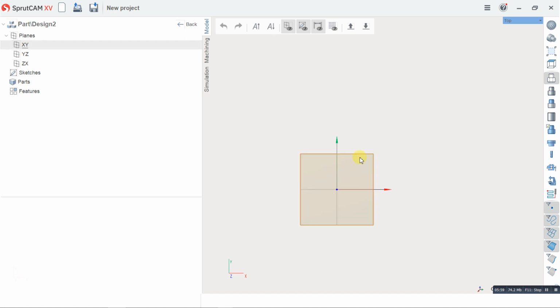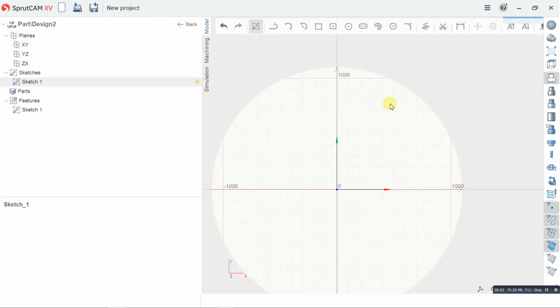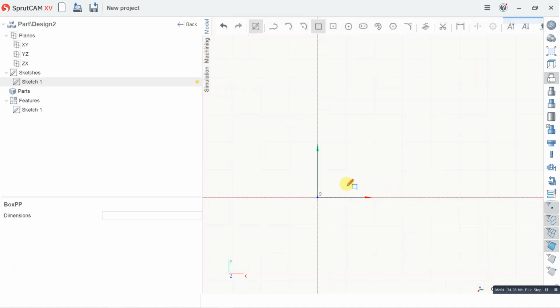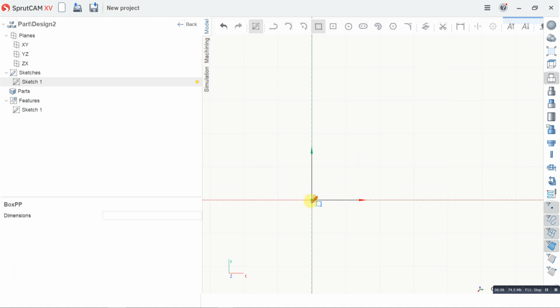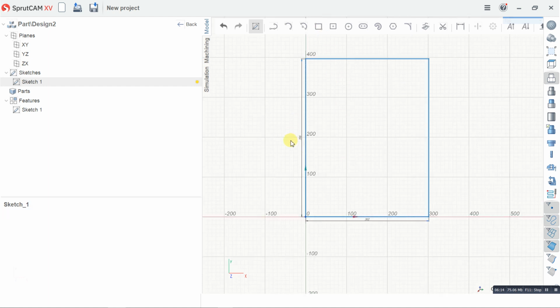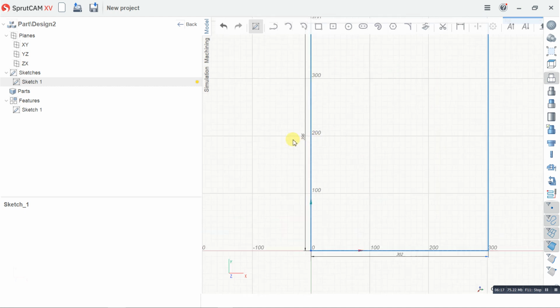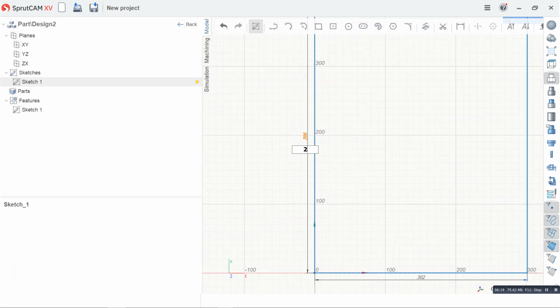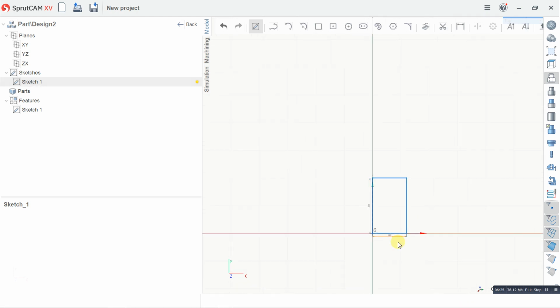Now I will draw a boundary. Okay, you can select the box by 2 points. Click on it, select the boundary, create a boundary that represents your drawing zone. So for example, I want to use a 200 by 120 boundary. That's all. Just click back and back.